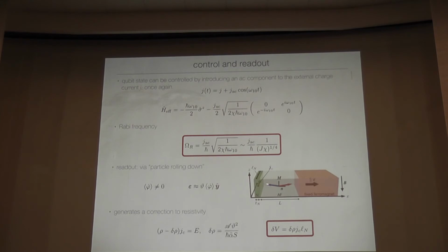Okay, so again, the particle rolls down once we tilt the potential steep enough, and to read it out, that means that this Néel vector is going to start precessing. As it rolls down that hill, that physically means that this Néel vector is actually rotating within the xy plane, and that's going to give rise to a motive force, and that's how one can read it out. And again, putting in the Gilbert damping and finding the terminal velocity for that particle to fall down that hill, you can calculate how big of a motive force you need to measure in order to read out this device.